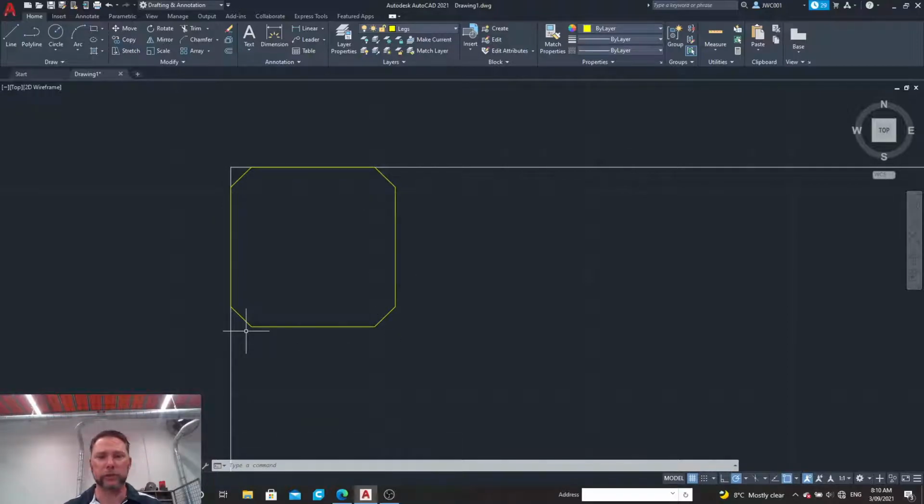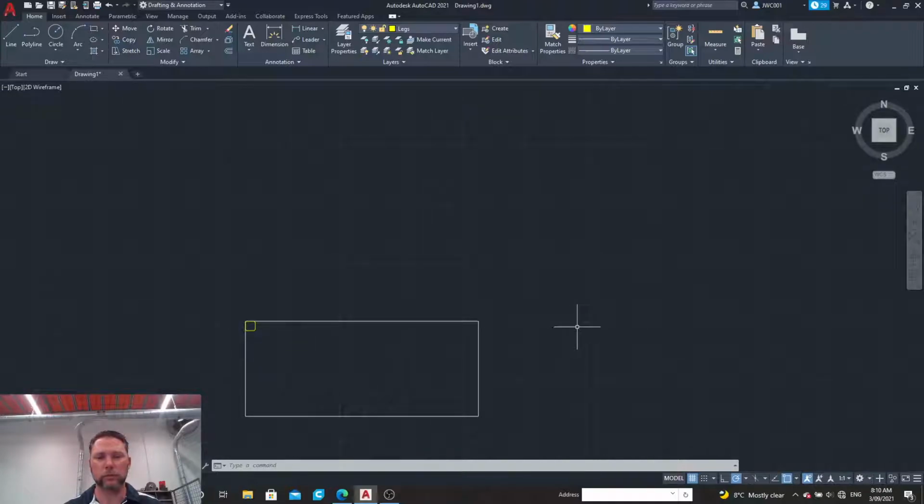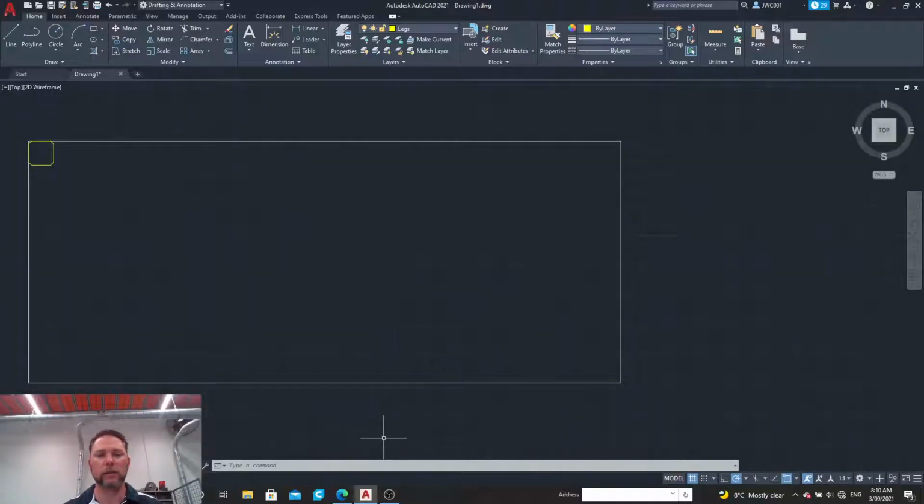Now I just wish to put the same thing there, there, and there. Now I could draw it and that would be fine. However, I'm lazy. So I'm going to mirror this. Mirror this here. Select it. So once I've done what it's told me to do, I've selected the command I want. I select mirror. Then I select my object because it says select your objects. Once I've selected my objects, I hit the enter key. That's me saying I've done that.